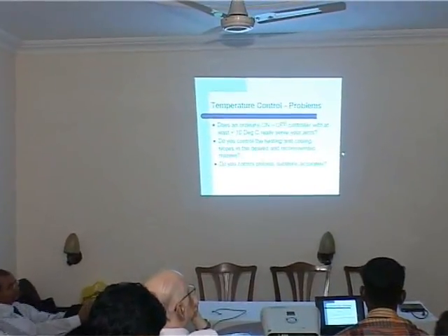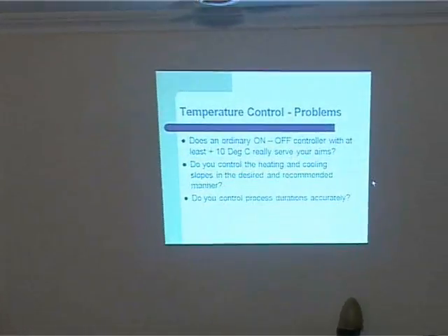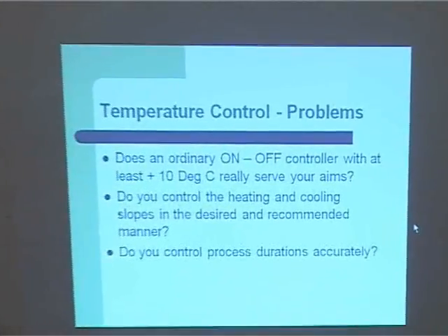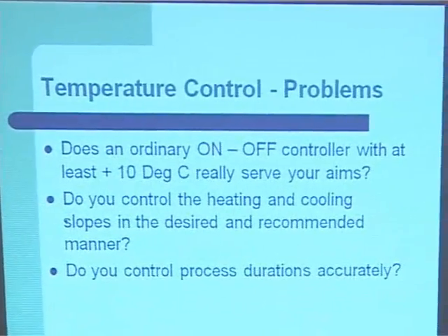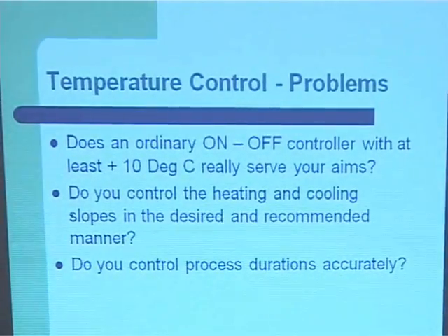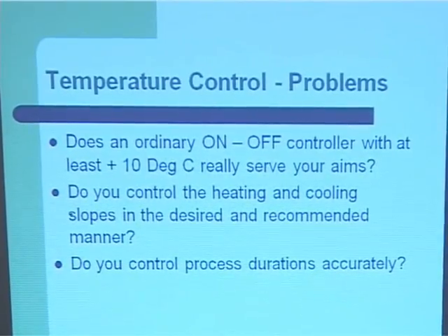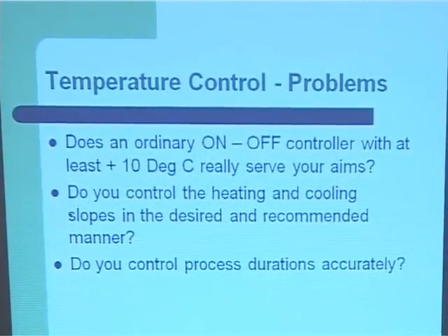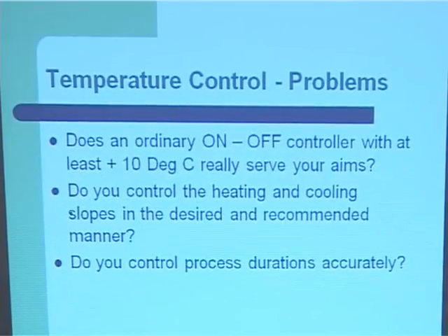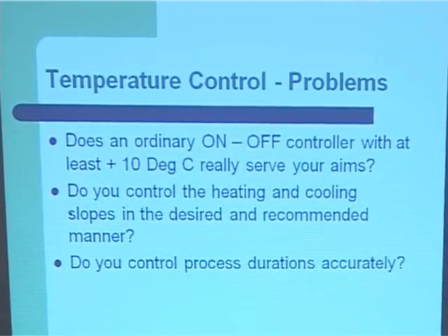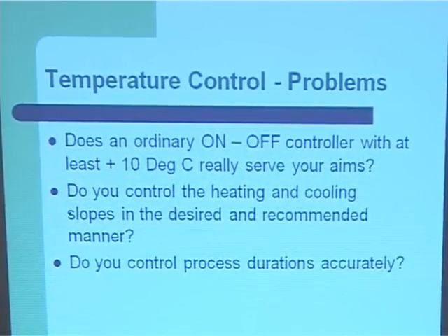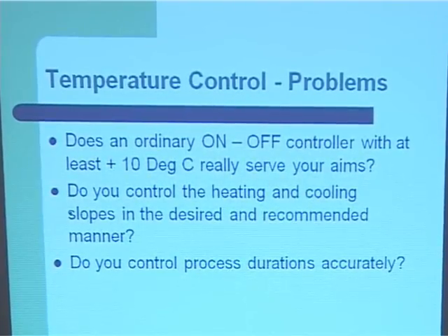It continues to go up. And then it starts cooling down. Natural cooling, there is no forced cooling. Natural cooling till it comes down to minus 10 of that set point: 925 minus 10, 915. Only then the contactor is on and the heating element on. So this variation of a 20 degree band, hysteresis, whatever we call it in instrumentation language, can be very, very crucial for